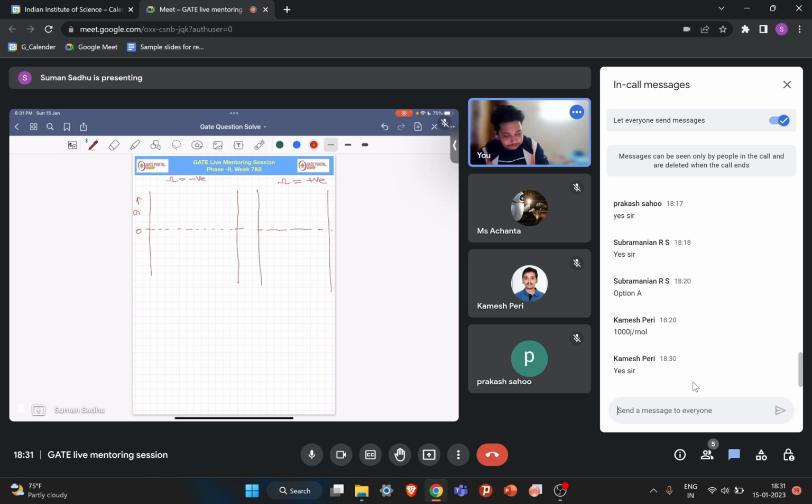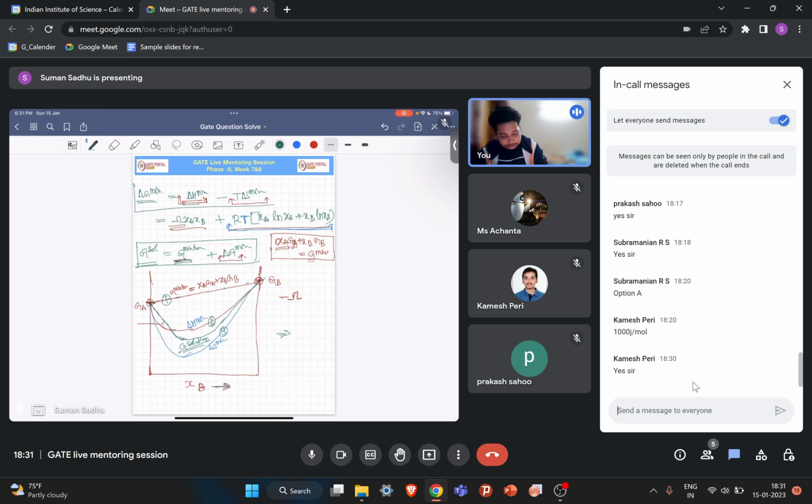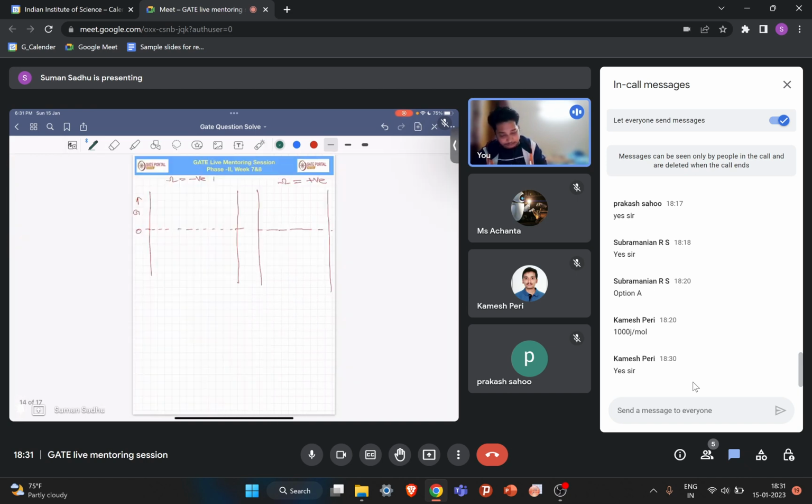So what is delta G mixing? Delta G mixing is delta H mix minus T delta S mix. I'm not writing the whole equation again; I think people have remembered this for now. So when omega is negative, that means your delta H mix is less than 0, negative, right? Let's say this is G, H, and TS. So the delta H will be negative, so it will be in this direction, and it is also a symmetrical function with your x. Delta H is omega into xa into xb, so it will reach its maximum or minimum at x equal to 0.5. It is a symmetrical function.